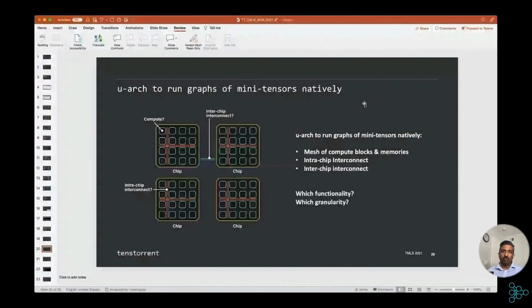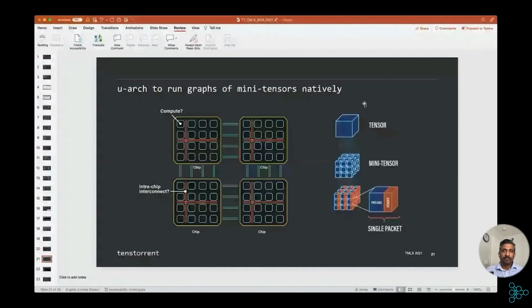That's the network on chip we have been developing, which provides flexibility of packet movement in a very seamless fashion, allowing us to move the tensor from one chip to another or within our own chip. You can see here an example where the tensor is broken down into mini tensors, but at the end of the day it's just packet movement. A header is added to the tensor, and it just moves across different cores, which provides the flexibility for scaling out across chips.